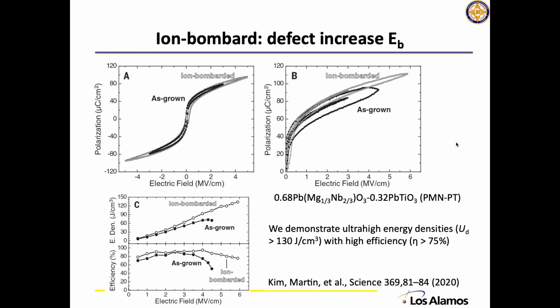They can actually increase the breakdown field to almost 6 megavolts per centimeter. And later on, you will see that our films can also achieve that. We barely can go above 6 megavolts per centimeter. I think that's kind of a limit in most oxides.